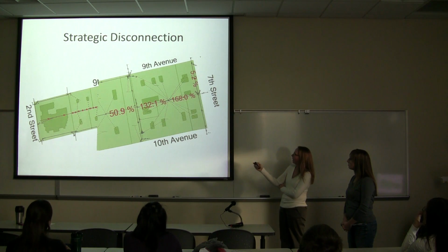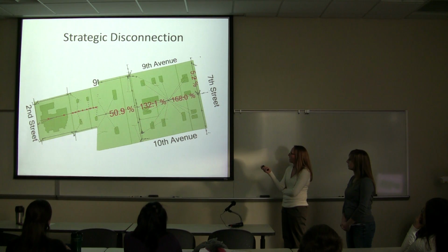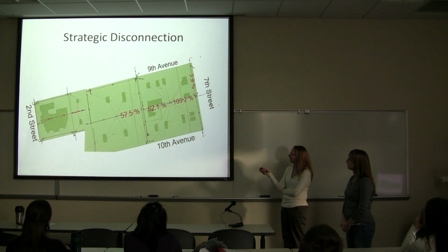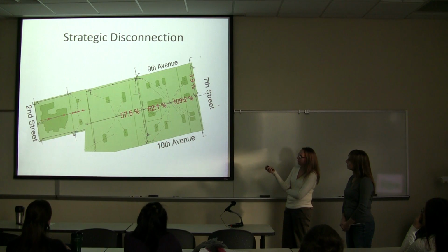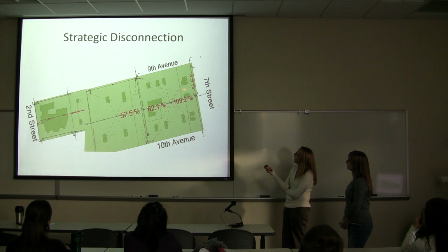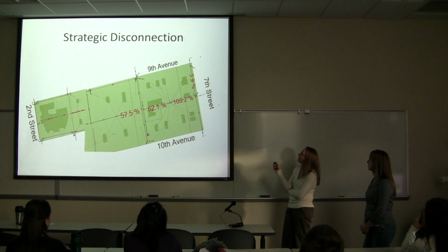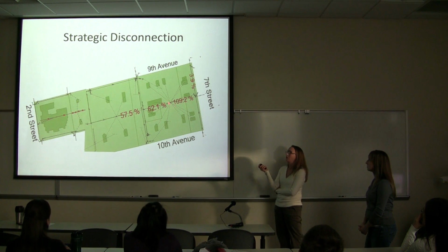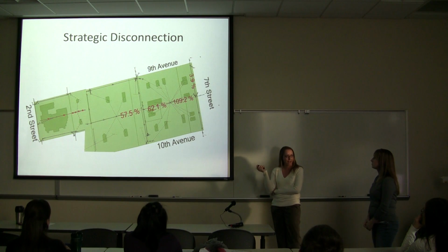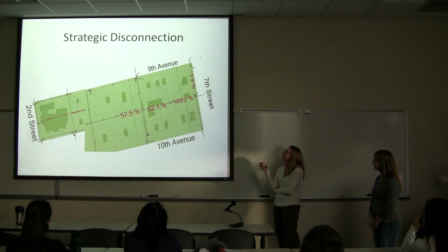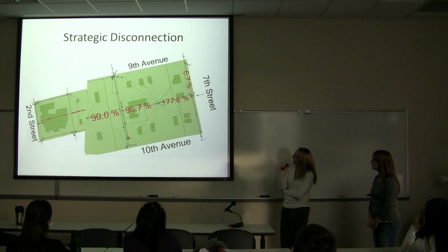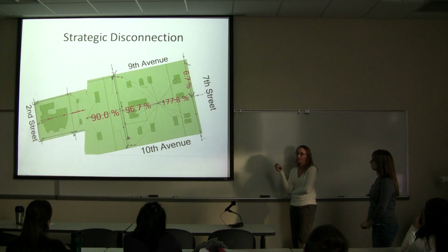significant, well, this is prior to moving it. We had 50% capacity here, but then it jumped drastically. So then after we move it from this combined catch basin to the storm catch basin, we didn't have such a drastic change. Now you'll notice here that it still says 109%, and I believe that this is due to the single catch basin that I talked about earlier, where it doesn't actually come into the network this way, but this provided an even slope for our pipe. So we like that.